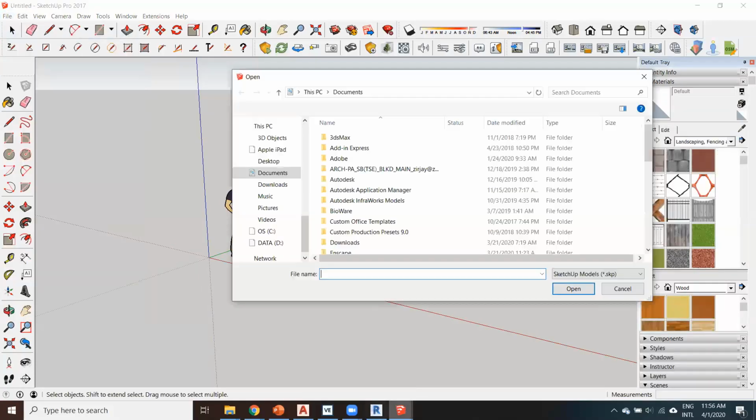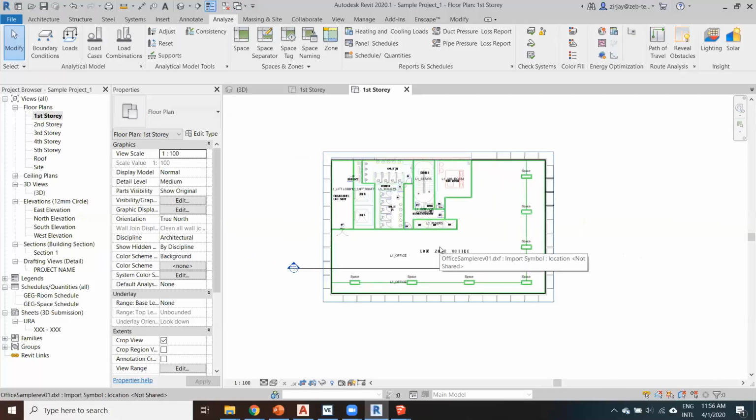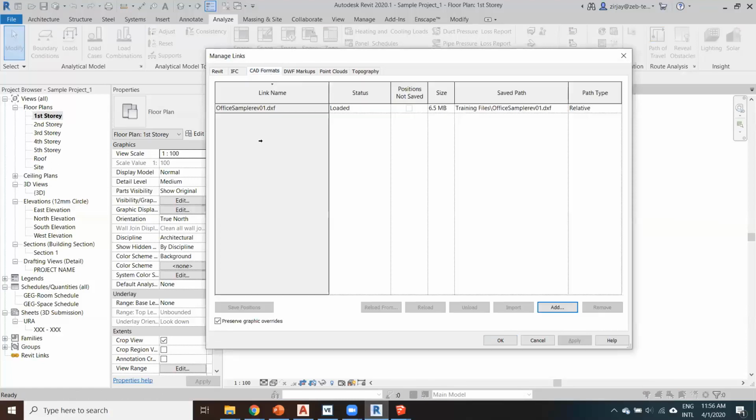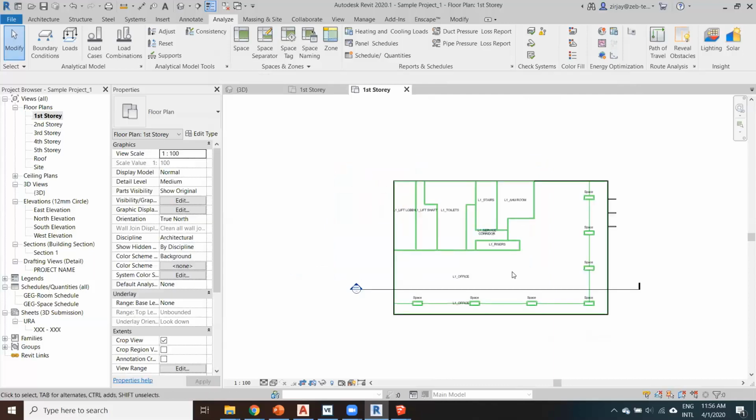Once you have the floor plans, you can see how easily we can assign a link in the CAD plan. And since it's 2D, it's light enough. Additionally, you may have many floor plans for the first story, second story, roof, sky terrace. You can unload them as needed. For example, once you've done the first story, you can just unload it to make it lighter on the program, and just have the current floor plan that you need loaded. So you're only working on that particular level, and it's going to be very light.